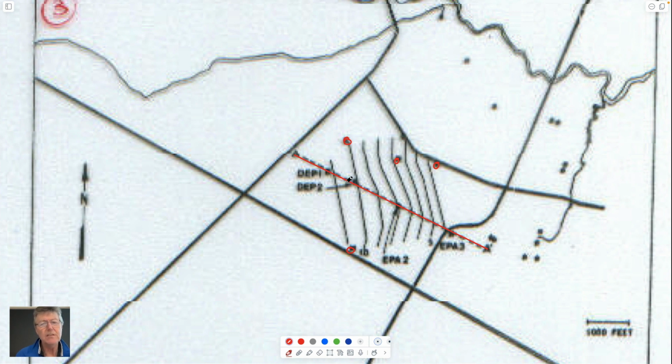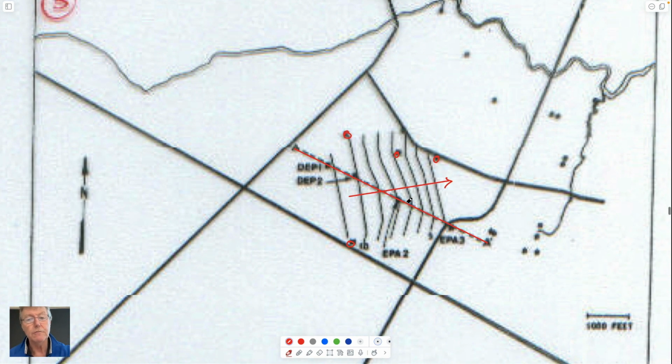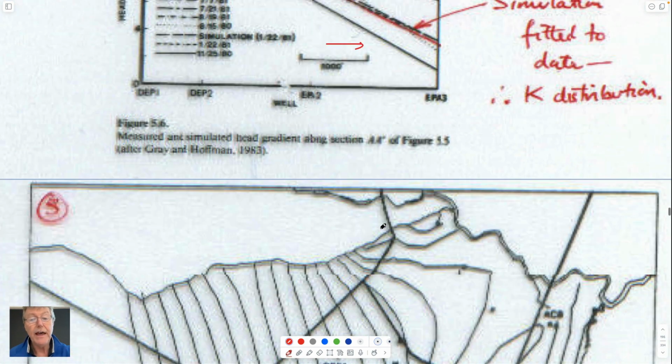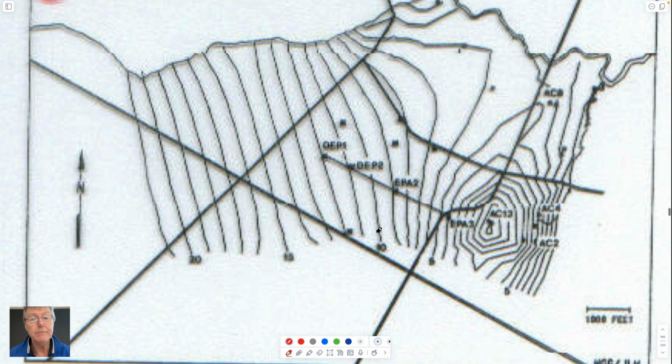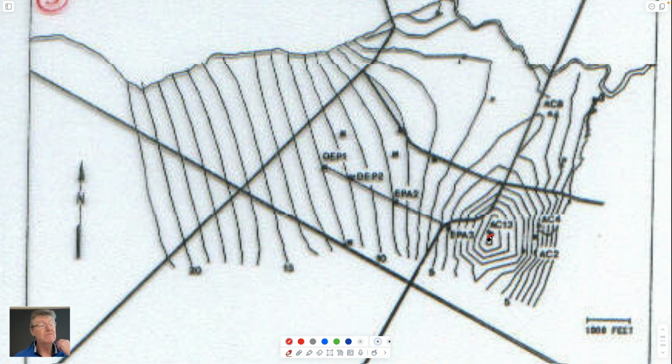You've done a little question like this on the BTEX one, where you had to decide which is the direction in which transport would occur, and you do it by drawing the contours, and you know that flow would occur in the direction of maximum flow velocity, which has to be perpendicular to the contours of equipotentials. So you do that, and then you perhaps do something like put a well in, start sucking water out. That will change the head distribution.